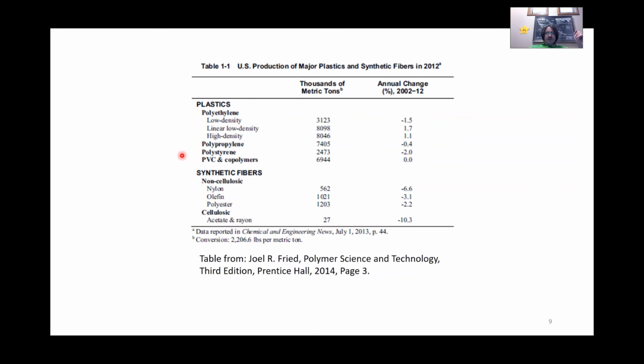PVC is another very common one, and if someone says this is vinyl, it's actually PVC that's been plasticized. A lot of times when people think of PVC, they think of rigid pipe. If you add a component called a plasticizer, you can make it less rigid and increase the applications. A very common application is synthetic leather or pleather, used for clothing and car interiors.